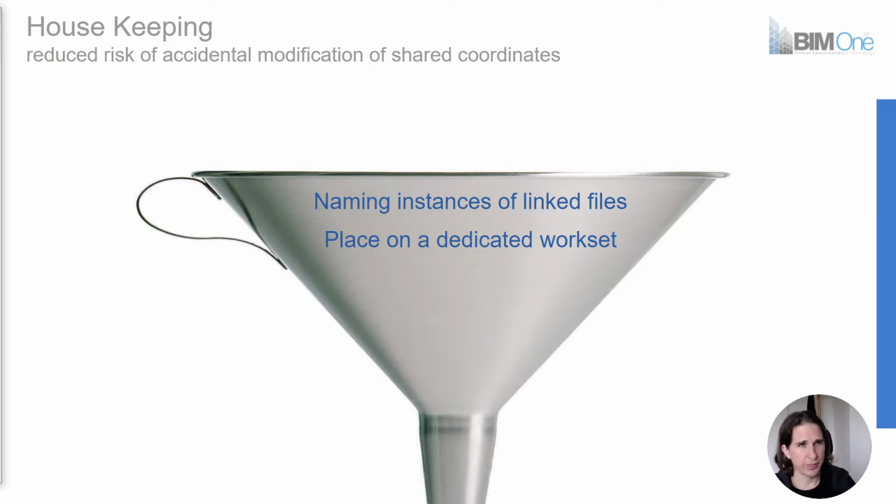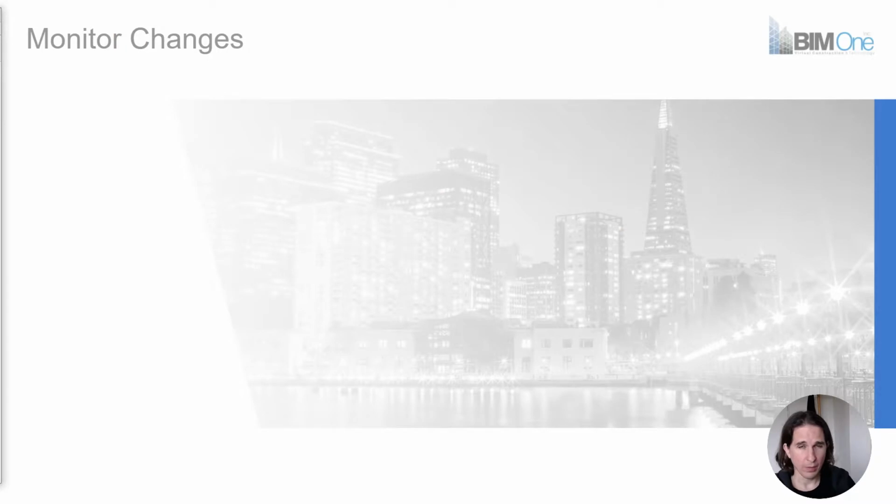You would also need to use a protection design option, except for the levels, so that you don't have any unwanted snap or movement. And also in the end to pin and lock in place the link file so that you have no unwanted movement as well. From there it looks like we're almost done, but we're not done quite yet.